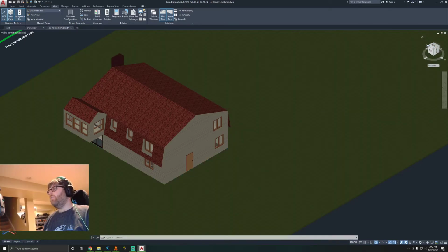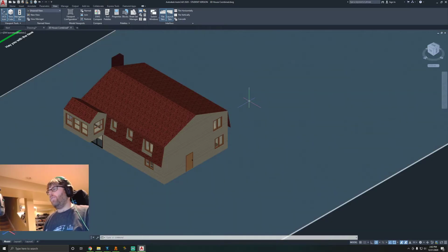I never use it because what ends up happening is you have this UCS and WCS, the User and the World Coordinate System in CAD. I don't know if this has been fixed, but I have noticed in previous classes that with students who end up using this a lot, CAD thinks you're drawing in, say, a front view, but it's displaying it in a top view.